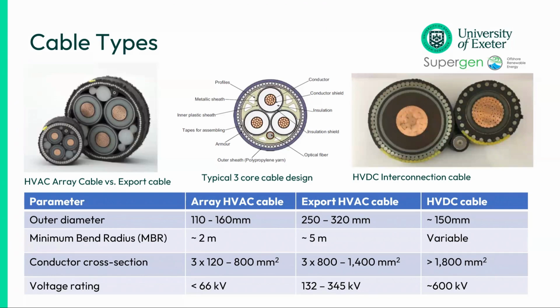The middle picture there gives you an idea of what I meant, that they're actually composites, if you like. They're heterogeneous structures, lots of layers. You've got the core inside. Around the conductor core, you've got a conductor shield, buffered by the insulation, buffered by the metallic sheath, and then you've got another typically plastic sheath. Some filling and profiles to keep those things in place.